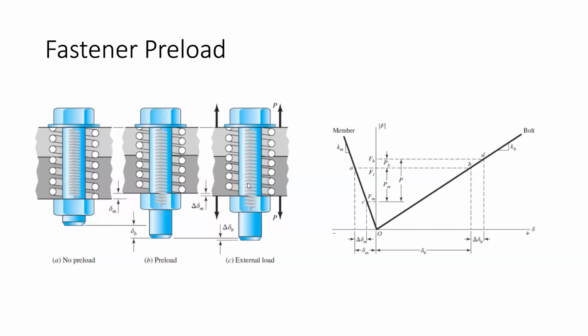And when you bolt into a thread, the threads actually don't distribute the loads evenly. So if I have a mating thread and a fastener, the threads at the bottom of the mating material, in this case the nut, this bottom part is loaded a lot more highly than the top part. And it's a little counterintuitive, but the reason behind it is that both systems have variable stiffness. So you can kind of imagine the fastener as a really stiff spring, and you're attaching that spring to the other threads of the mated fastener or the mated thread. And because those two springs don't have matched stiffness, the load on the bottom tends to be more.